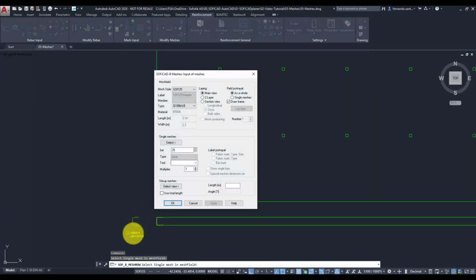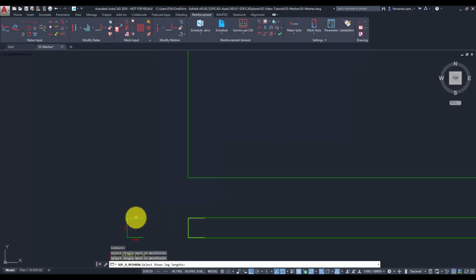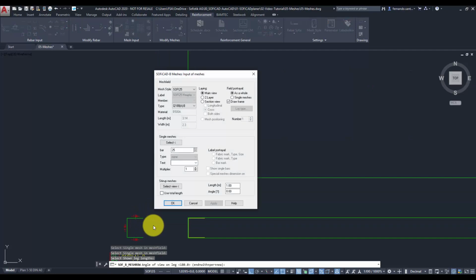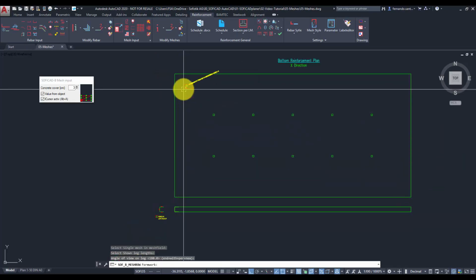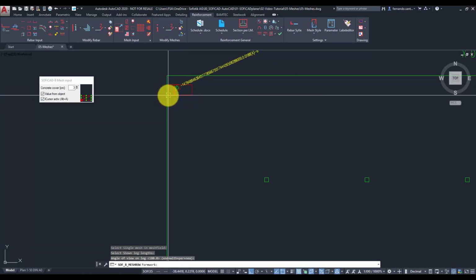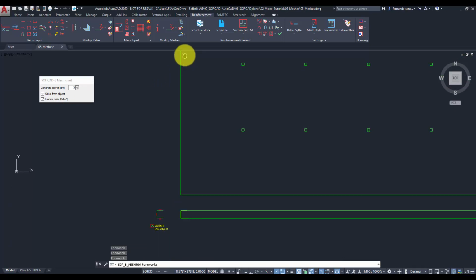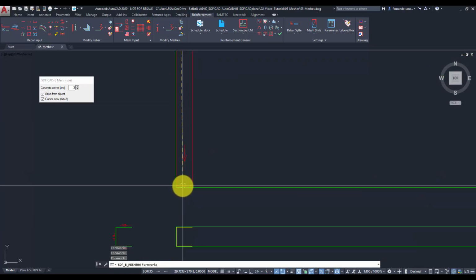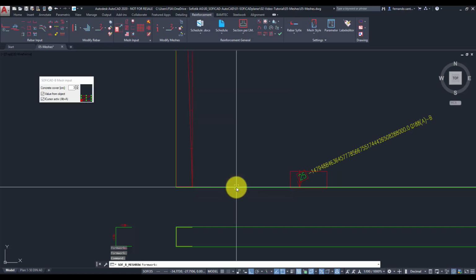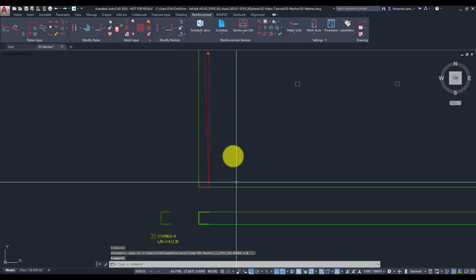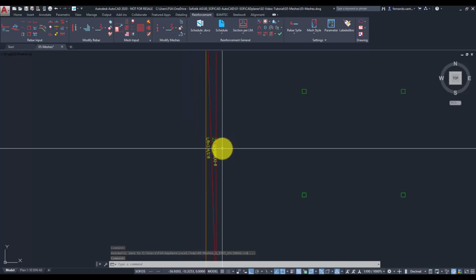We start by selecting the mark we want to place, and then its view. In this example we want to represent the top view of the mesh, so our mesh row will be 1 meter wide. As we see 12.9 meshes are needed.